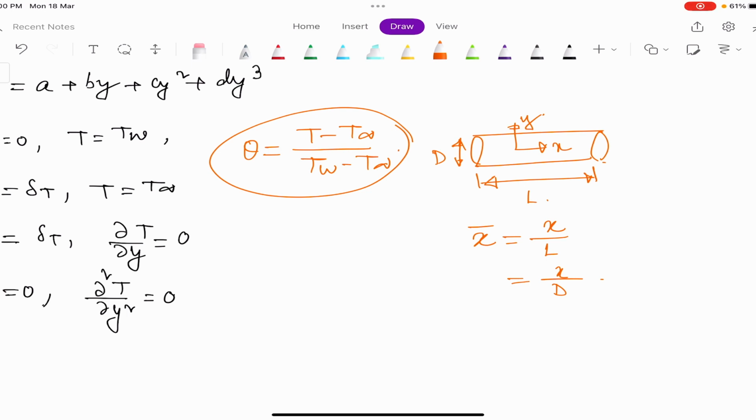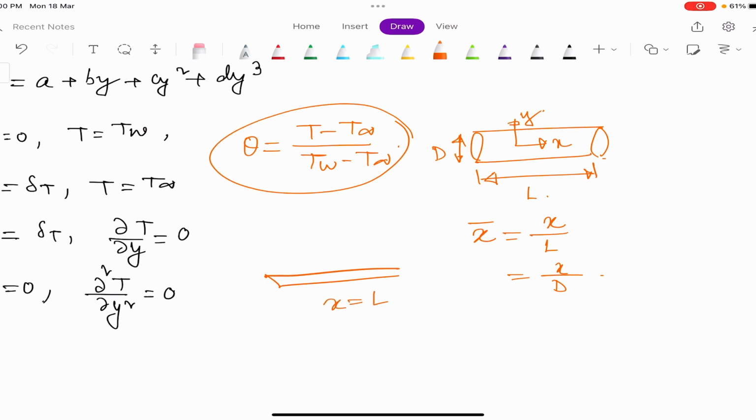Like in the boundary layer we know that for x we should take the non-dimensionalization variable as L. Now inside the boundary layer, if you take y also as L, there will not be any mistake in terms of mathematics, but the physics will not be depicted by that non-dimensionalization. So non-dimensionalization should obey the physics.